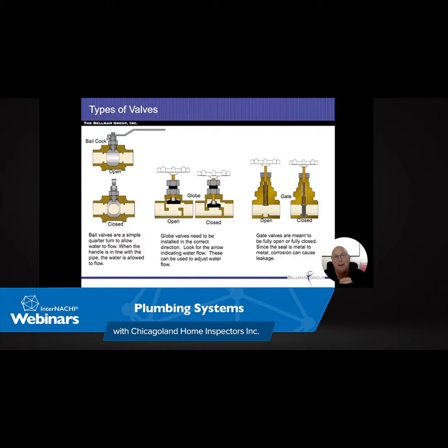We double it, it would be 0.4. And then you can see on the 3/4 inch pipe at the bottom, it's actually bigger than 0.4. So it's more than twice as big. So bigger pipes, easier flow of water, less friction loss, and greater amount of flow. And this is where they're talking about depending on the pressure and the gallons per minute. And friction loss is directly related to the gallons per minute. So the more water flow through the smaller hose, the more restrictions we're going to have. And that's kind of what this chart is explaining.